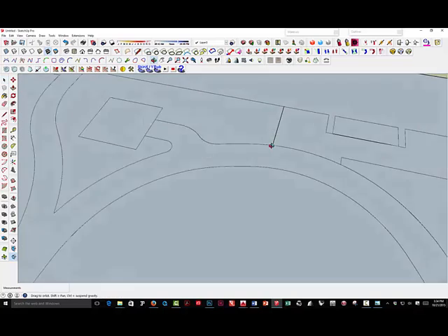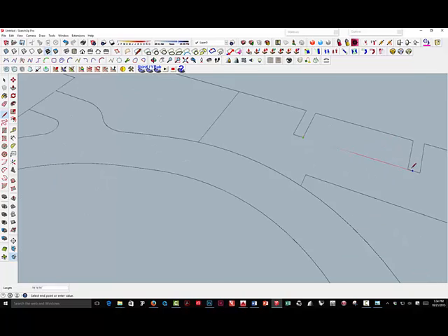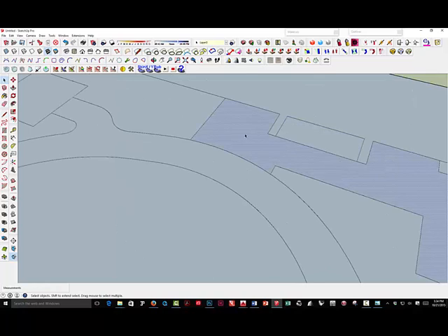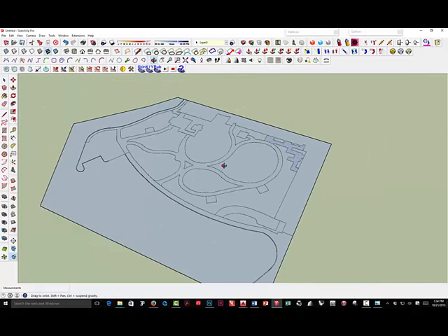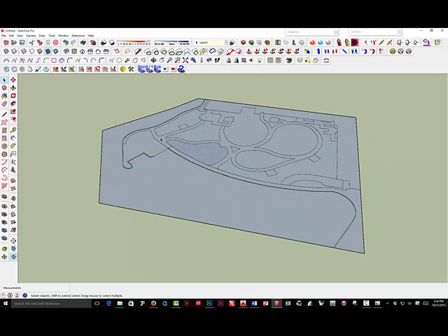And then any place you see thick lines, like this one's kind of doing weird things, I'm going to get rid of that. Put that in there, get rid of that. I know I've got an endpoint. This is one where you have to really zoom in and make sure you get right to the endpoint. And now I've got those all separated out as well. Okay, that's the goal. While it's a flat surface, get rid of those pieces and all the little extra parts so that I can select each piece, each area, and it selects as a separate area, just like in the last exercise.